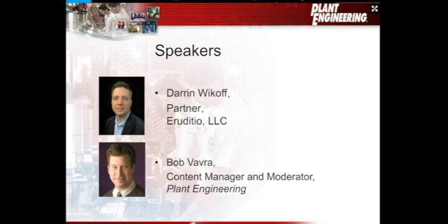If we're using the significance analysis result, then it's similar to the example: I'm not so much concerned about the score, but I'm looking for common characteristics, whether that's spares lead time or quality impact. I'm looking for the common characteristics across the plant or across the business unit and trying to figure out what my asset management plan needs to be. An asset management plan is not just a maintenance plan. It's really how do I mitigate that risk. So those are the different layers that I would start with.